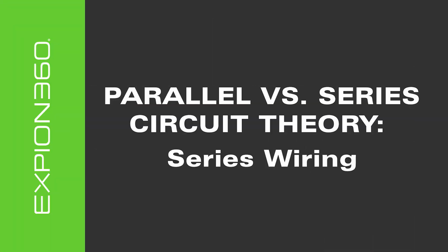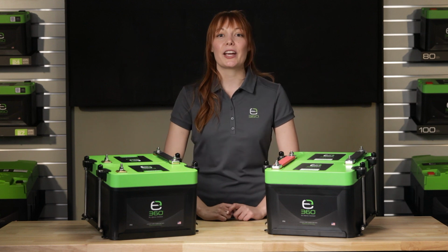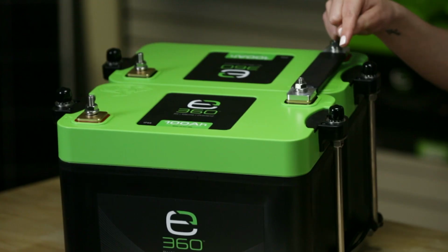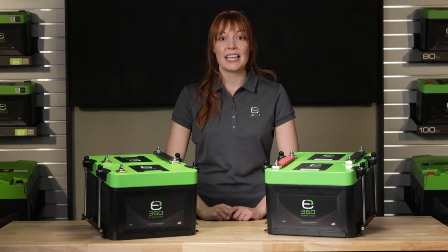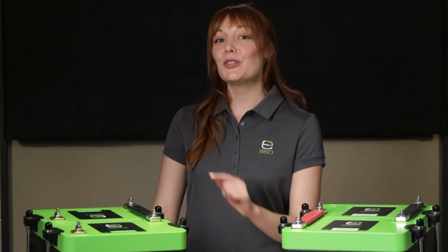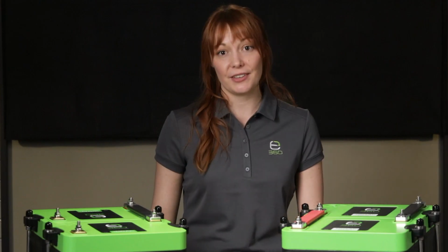Let's go to our series wiring example. In a series wiring configuration, the individual battery terminals are connected positive to negative in strings of up to 4 batteries. In series, the voltage increases, but the capacity remains constant. In this example, two 100 amp-hour batteries total 100 amp-hours at 24 volts DC. We are using a bus bar here, as well as in the previous parallel example.